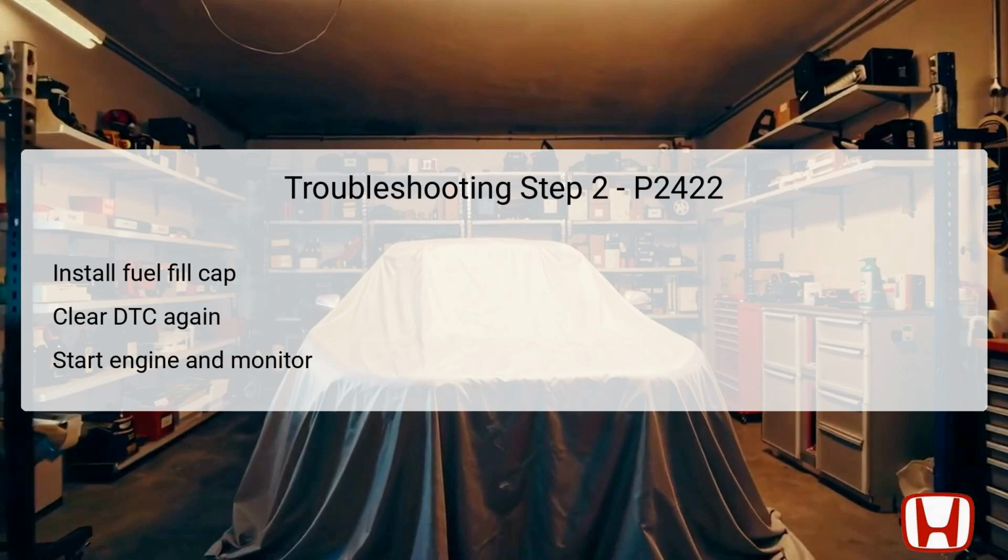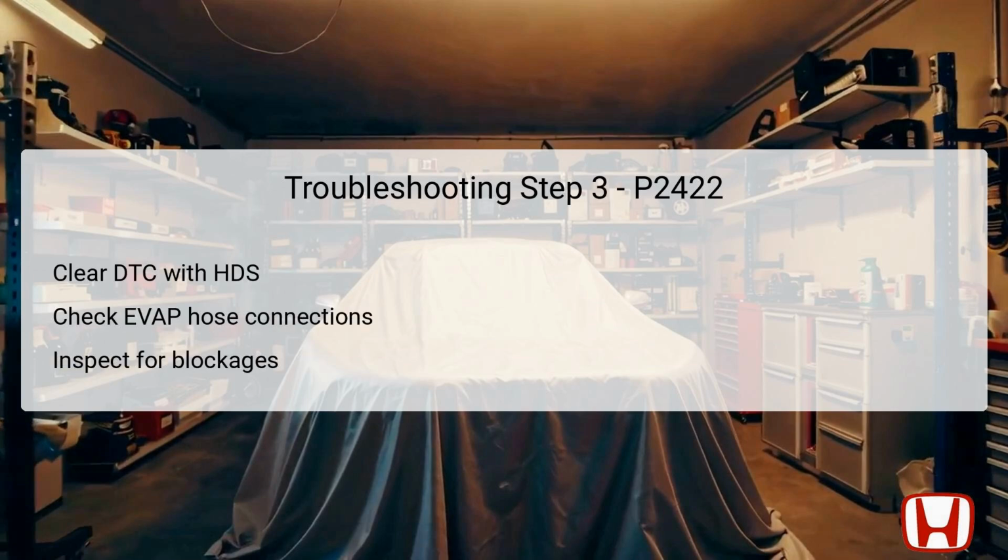system is functioning correctly. In step 3 of troubleshooting, start by clearing the DTC with the Honda Diagnostic System, HDS, again. This prepares the system for a fresh evaluation after verifying the function of the EVAP system.